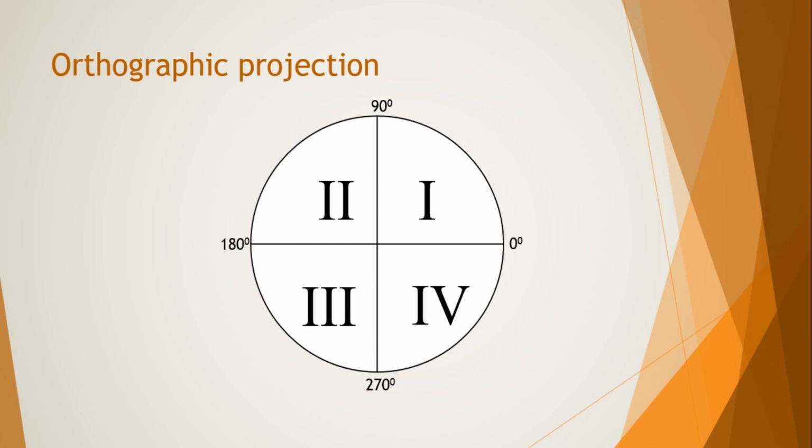We will not be using the second and the fourth quadrants, because these complicate the drawing views, where one view is placed on top of another, and this complicates instead of making the viewing much simpler.